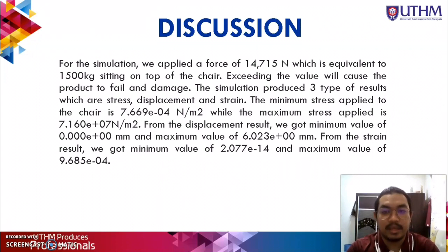To get the maximum force, we used trial and error. We started with 100 newton and went up to 14.715 kilonewton. We got no failure in the product.